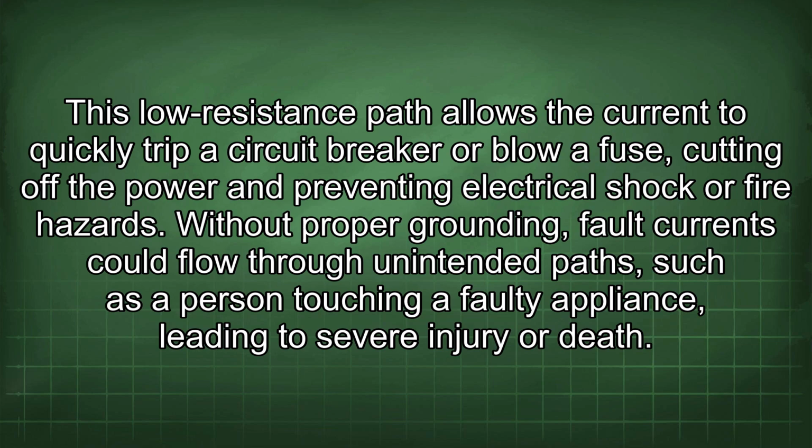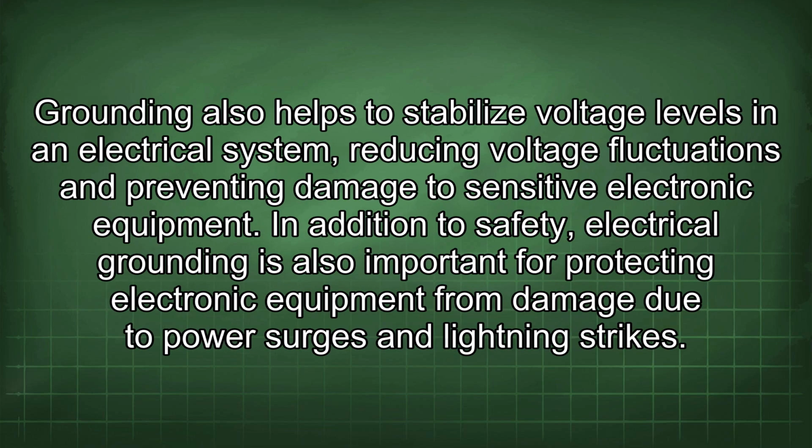Without proper grounding, fault currents could flow through unintended paths, such as a person touching a faulty appliance, leading to severe injury or death. Grounding also helps to stabilize voltage levels in an electrical system, reducing voltage fluctuations and preventing damage to sensitive electronic equipment.